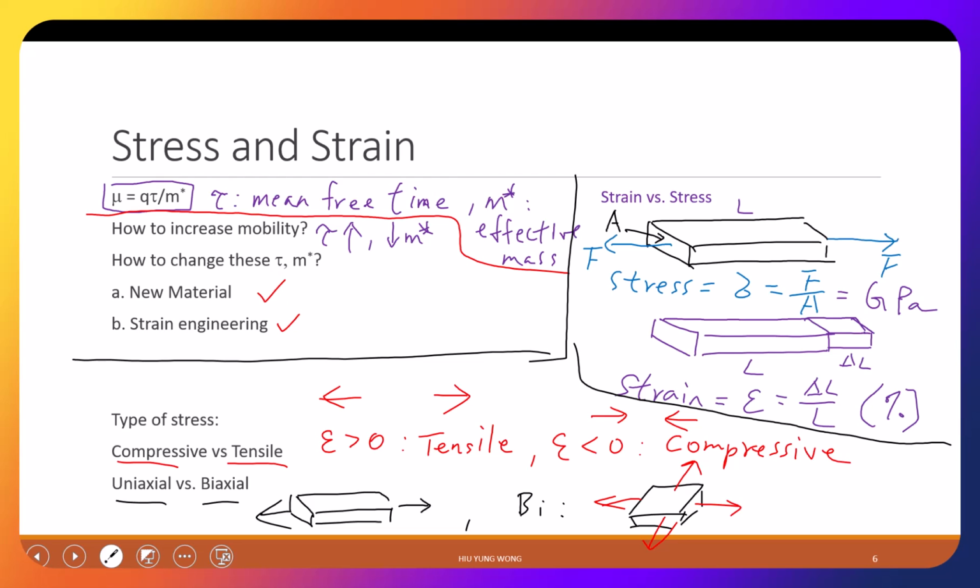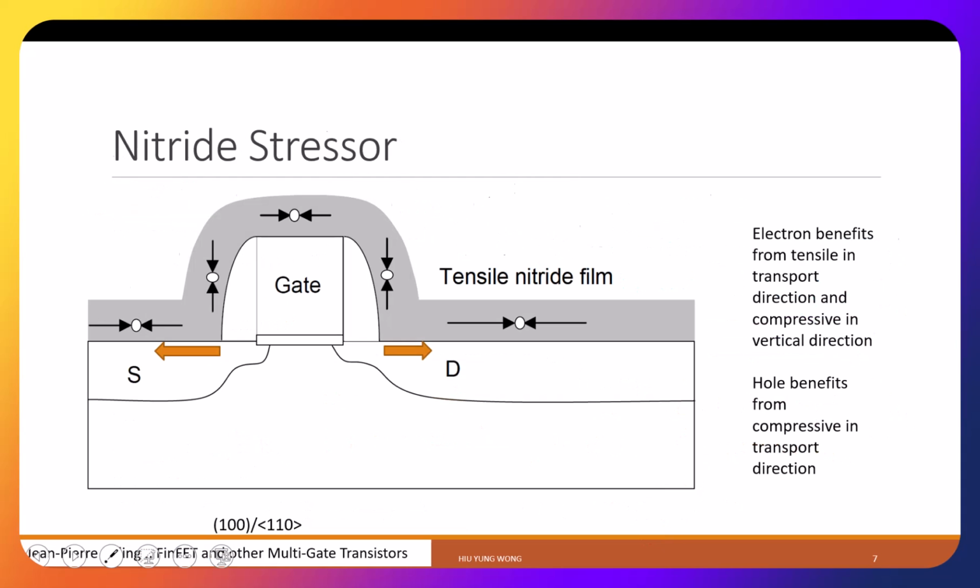Isn't that a strain in the orthogonal direction? So you do have this so-called Poisson ratio. It is talking about you pull in one direction, how the other direction changes relative to the direction that you are pulling. Poisson ratio of 0 means that the other direction does not respond to your stress. Okay, good. So we want to understand this.